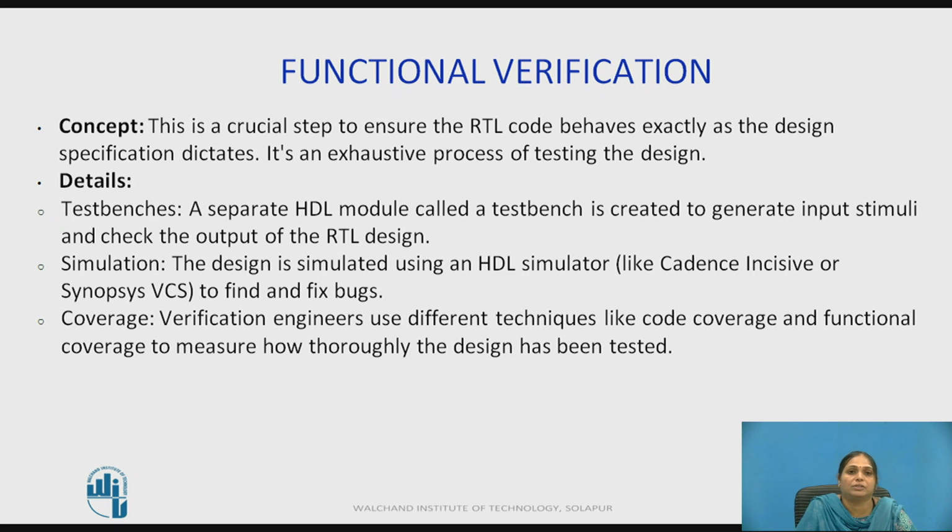Functional verification is a very important step to ensure the RTL code behaves exactly as the design specification dictates. It is an exhaustive process of testing the design. A separate HDL model called a test bench is created to generate input stimuli and check the output of the RTL design.